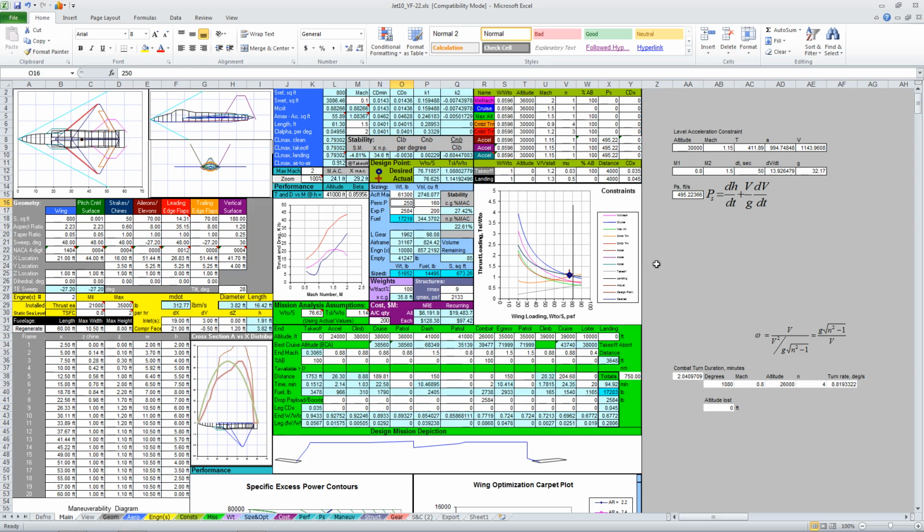Now, one thing that's limiting me right now is the landing distance. But remember in the other video we said that actually we would be willing to just have the sum of the takeoff and landing distance be 8,000 feet, the length of the runway. That allows us to accelerate for takeoff, reach takeoff speed, and then abort on the remaining runway. Right now our takeoff distance is like 1,700 feet, and it only takes 3,600 feet to stop.